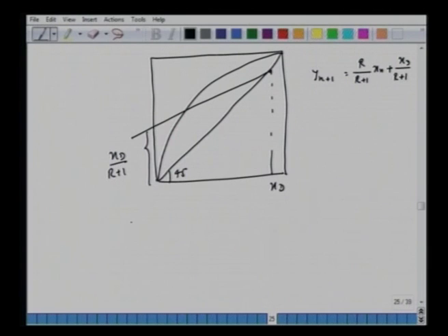In the earlier case, similarly, we took this Xw and took the slope to connect to this point here, which if you extend and connect to Xf will give you the Q line. But notice that now at the bottom we have this L bar, which is the same as W, with composition XW, but the vapor which arrives has a composition of 0.